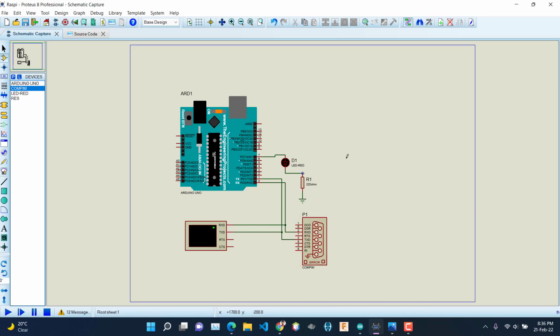Okay, so now the idea behind simulating Nodemcu is you need to upload the code into your Nodemcu. I am using the Nodemcu version 3 for this demonstration. You can use any version of Nodemcu. What it does is you upload the code into the Nodemcu, and then you interact with the Nodemcu and send the data serially to your computer. Connect your Nodemcu using the USB cable, note down the port of the Nodemcu, and select that port here.